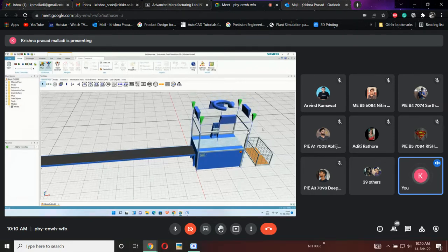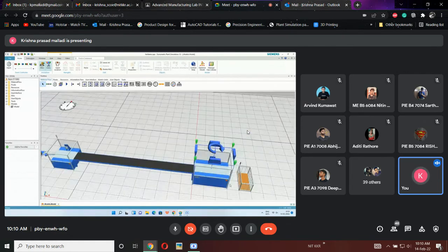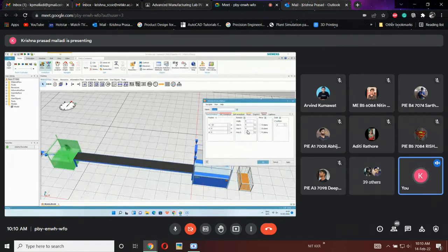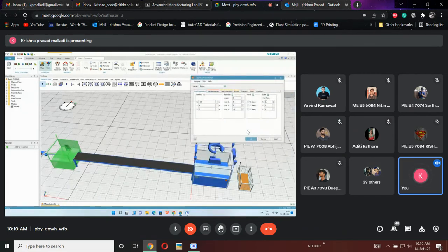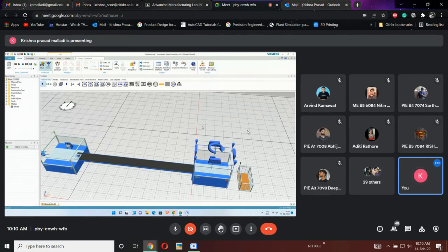But you don't know how much you are increasing it. So whenever you want to increase the height, breadth, length, or other machine characteristics, the correct method is to enter into machine properties. In that there is an option, Uniform. Deselect it and you can directly give values here. If you want to increase 1.5, 1.5 and 1 itself, then enter 1.5, 1.5 and Z will be 1.